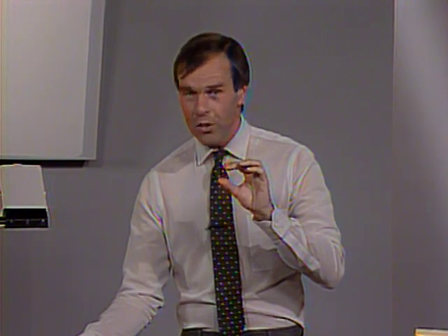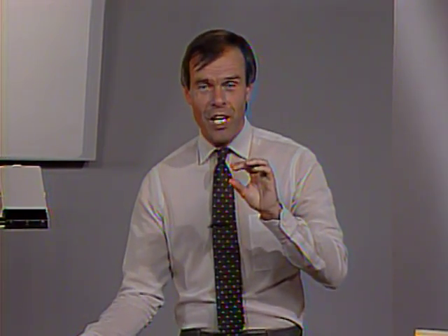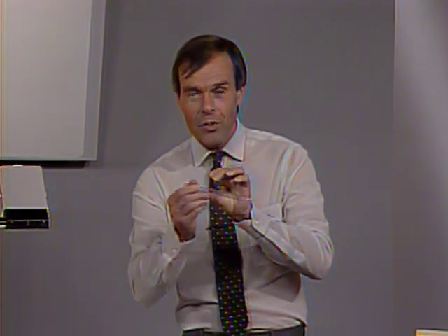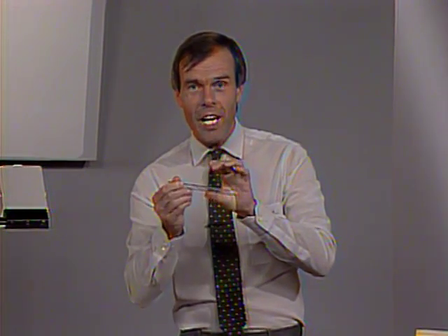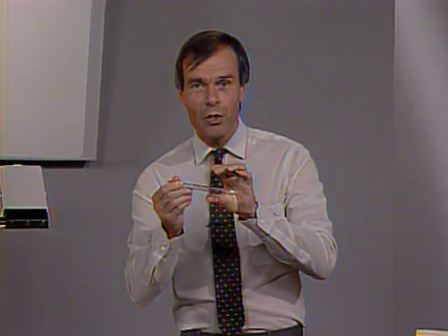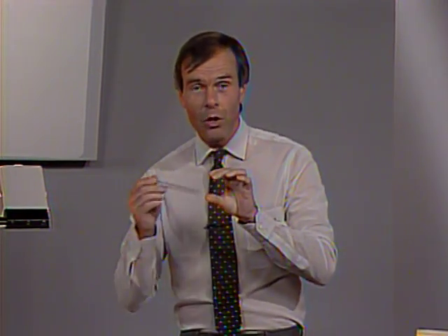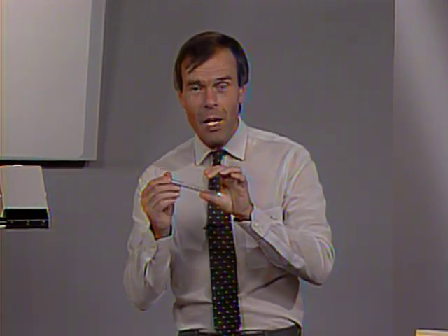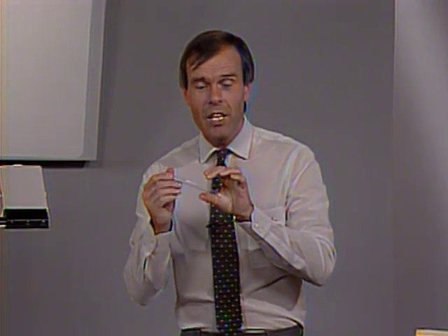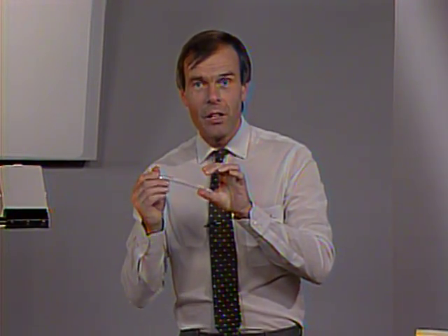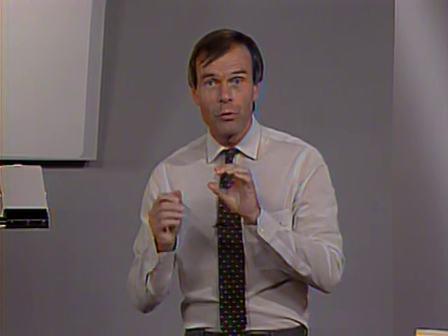So a stress that should be 0, really, because tau zz should really be 0. It's the stress in the transverse direction. The wave travels this way, and tau zz is acting that way. This stress should be 0. We find actually that it grows, and it grows because we are using a time step that is larger than the critical time step that should be used for this problem.